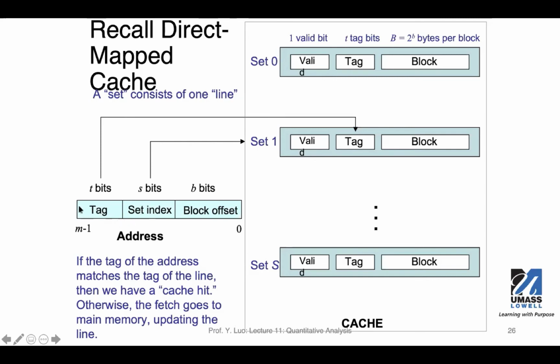So when you access a certain variable in the memory, you tell the processor, okay, this is the address you will need to use to access memory. Then the processor will take this address, segment it into several parts, and use first the set bits to find out the set. And because we use a direct map, we only have one tag in the set, and that corresponds to the block. And then after these B bits and S bits, the rest of the bits are the tag.